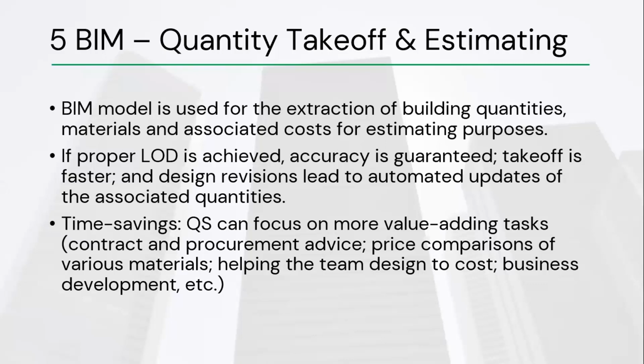The process involves generation of quantity takeoffs from the models and linking this to a cost database to compute a cost estimate. BIM cost metadata can be exported to QS software, such as CostX, where the QS now manipulates the model to extract building quantities and add descriptions from their database and come up with a bill of quantities.